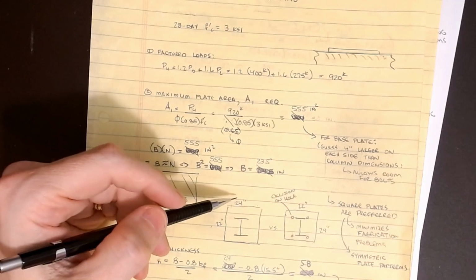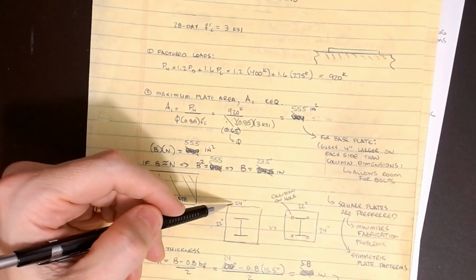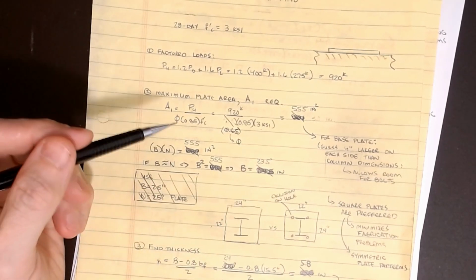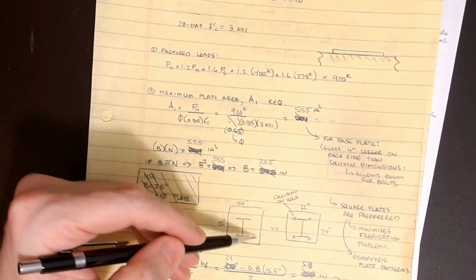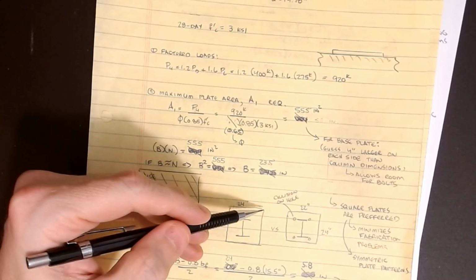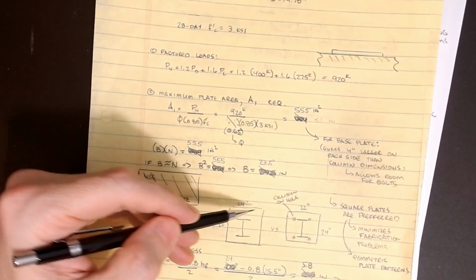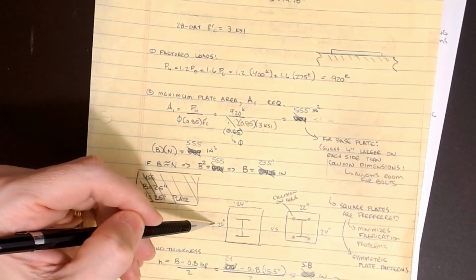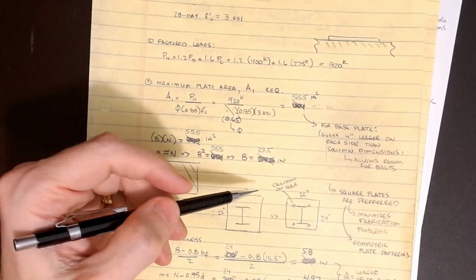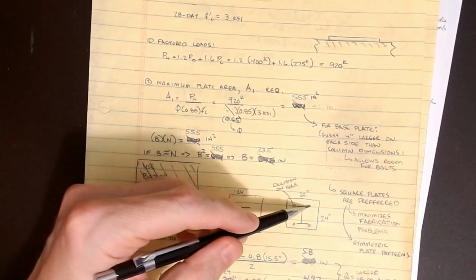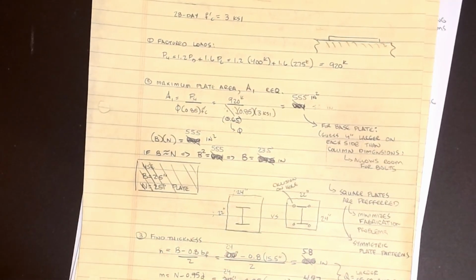So what they do is that when they fabricate these plates, there's one guy that's cutting the plate to the shape he needs and another guy that's putting the holes in, and then there's a third guy or group that is welding this plate onto the column. So if this is 24 by 22, it's real easy to get this thing turned the wrong way. Okay, and then when that happens, your bolt holes won't line up with the anchor bolts in the bottom.